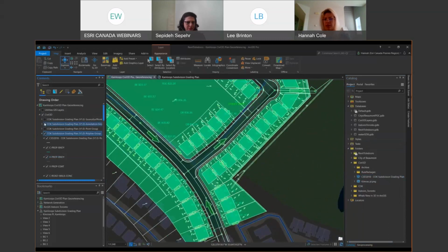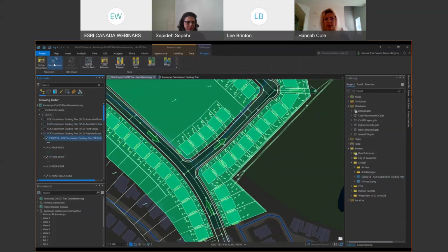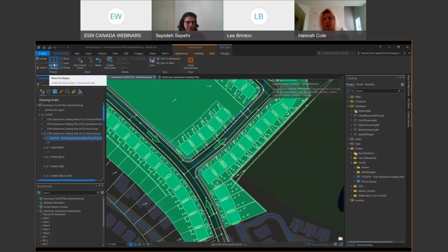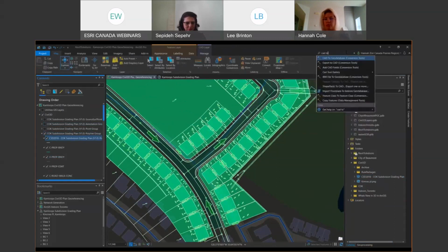It is a best practice I have found to use either a polyline or a polygon layer inside the Civil file. And as a tip, creating bookmarks in your project will help you navigate your maps with ease when you georeference. Ensure you use the Define Projection tool as well if your Civil 3D data does not already come with a coordinate system previously defined.